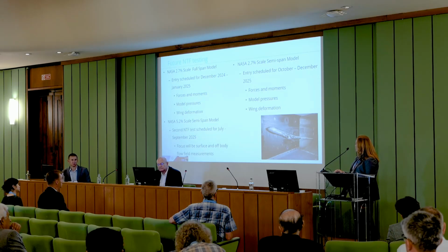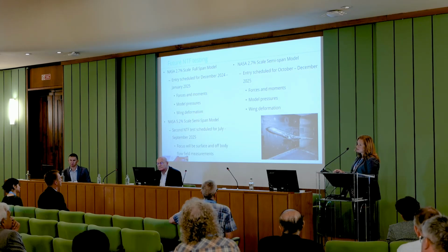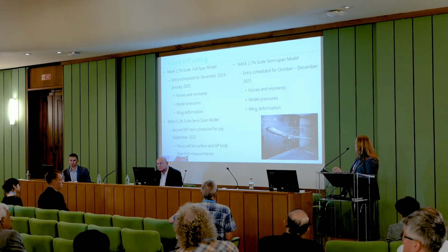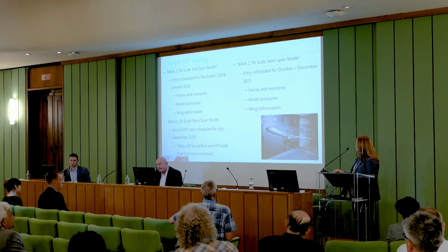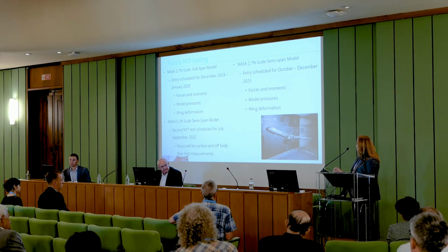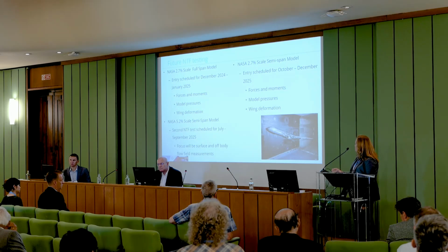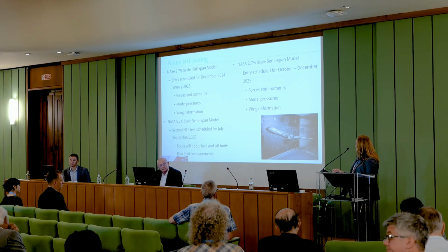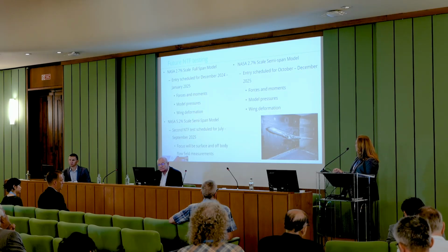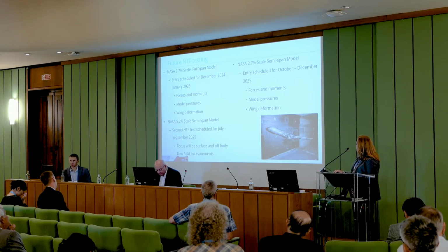Okay, and then the final test, as of right now, will be the 2.7% scale semi-span test, where we're going to take that same port wing and test it on the wall, as you see here. That entry is scheduled for late 2025, and there we will focus on force and moment, model pressures, and we'll take wing deformation and compare what we get from that semi-span test to the 5.2% semi-span test.